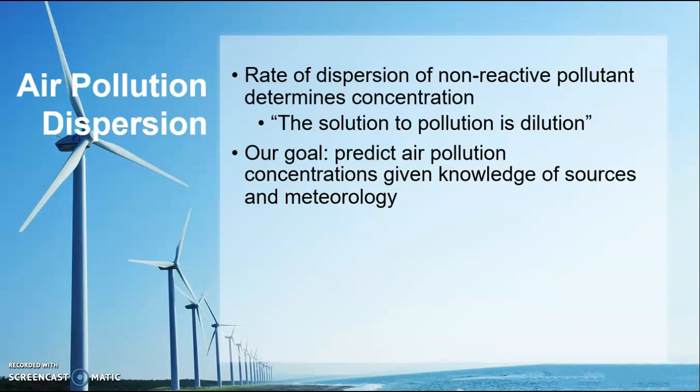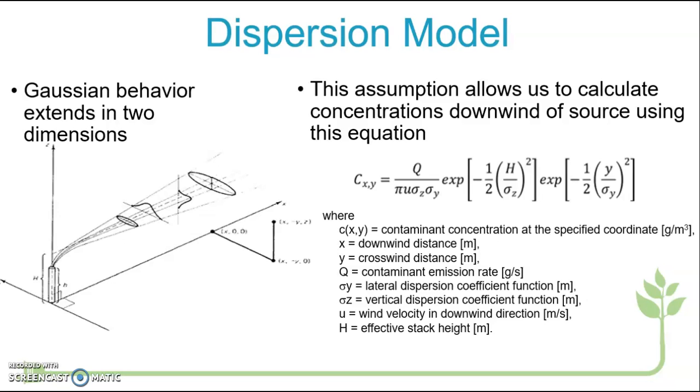That was explained in part 1 of this chapter. This part is on how you are going to treat or control the air pollutant concentration. This is the dispersion model that you are going to use either to calculate the contaminant concentration, or, given such a concentration of contaminant, to find how high the stack needs to be built in order to have an allowable concentration of your contaminant.